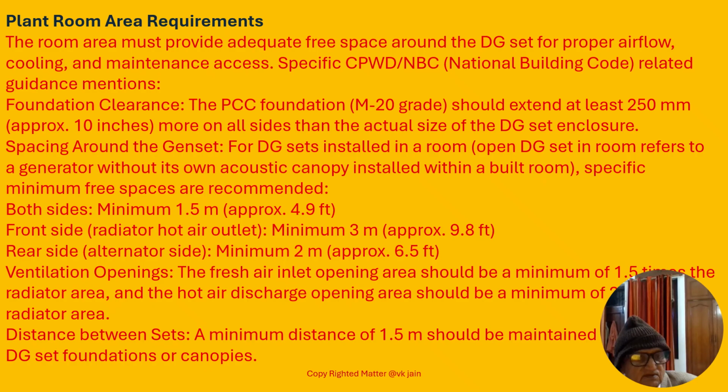Both sides minimum 1.5 meter, front side where the radiator hot air outlet is there minimum 3 meters, rear side minimum 2 meters.